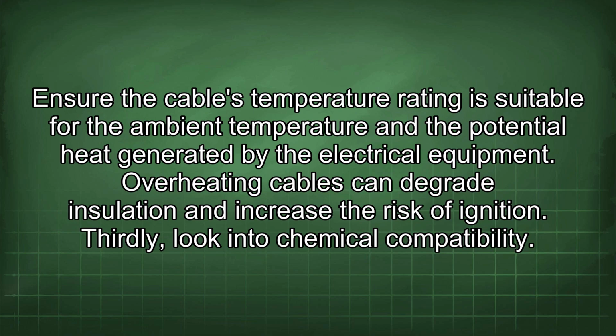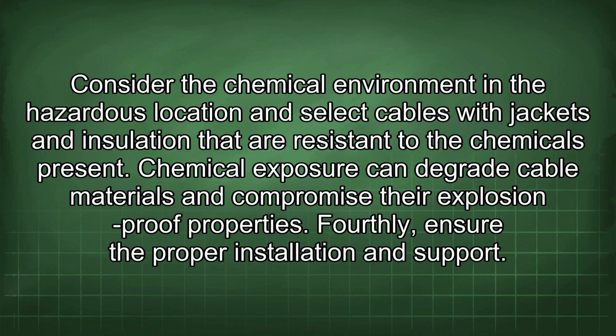Thirdly, look into chemical compatibility. Consider the chemical environment in the hazardous location and select cables with jackets and insulation that are resistant to the chemicals present. Chemical exposure can degrade cable materials and compromise their explosion-proof properties.